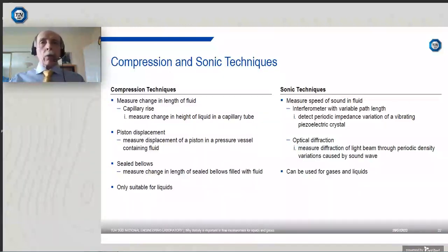Sonic techniques are where you measure the speed of sound in the fluid, and that can be done either using an interferometer with a variable path length or by optical diffraction, because there are thermodynamic relationships between the speed of sound in a fluid and its density. And these sonic techniques can be used for both gases and liquids.